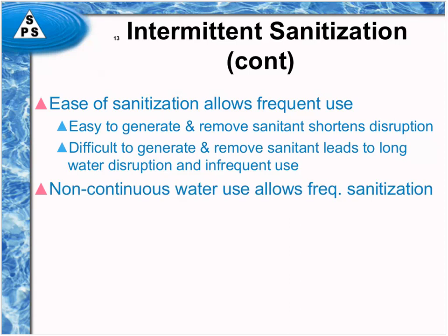If you do have a particular shift or work schedule such that water is not being used 24/7, then your water system has periods of time in it that can be used for sanitization. For instance, if you have a daily schedule opportunity, like you run a 2-shift operation, or you run a 3-shift operation but the 3rd shift is only cleanup, or something that doesn't use water, like on a night shift, then you can sanitize at night.